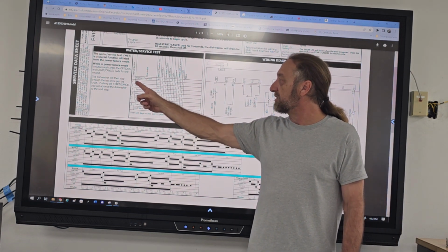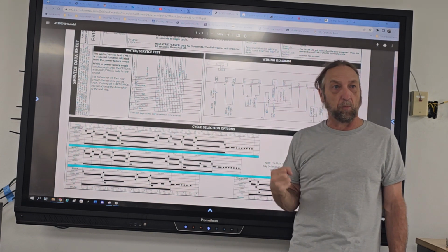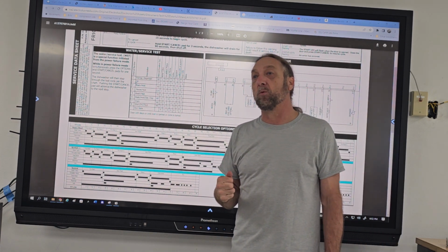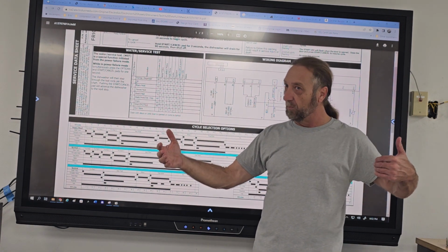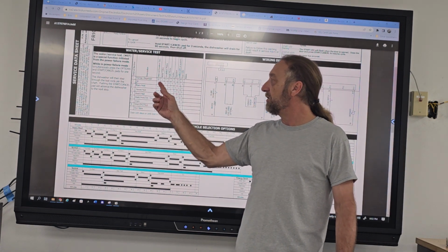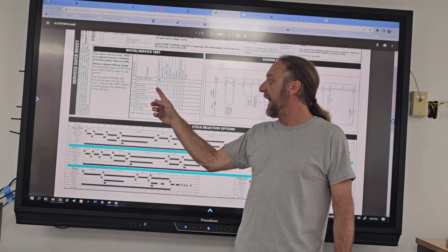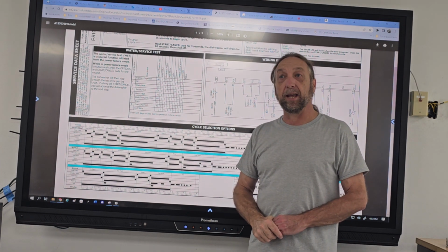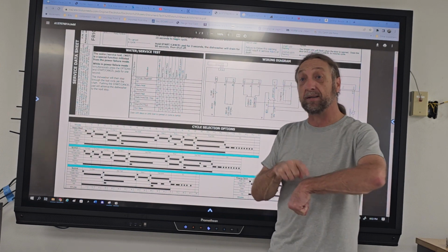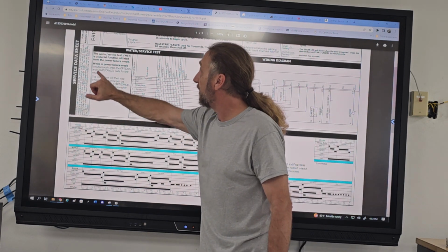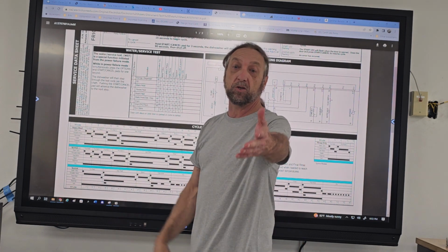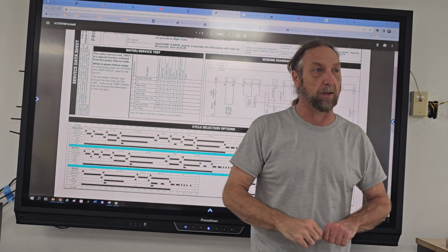After that, it's gonna go to step 2 and it's gonna fill some more for up to 27 more seconds, because most fill cycles are 1.5 to 2 minutes long. So they continue to fill. So after 1.5 minutes, the water comes off and the heater comes on. So I could almost time myself on my watch, go into the diagnostics, and here's the instructions on how to do it. And when we get this one back together, if you want, you guys can try to do that.